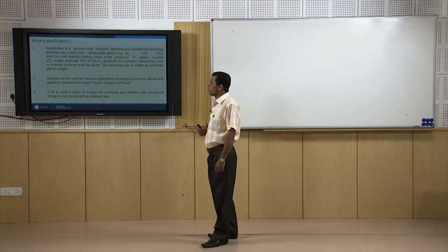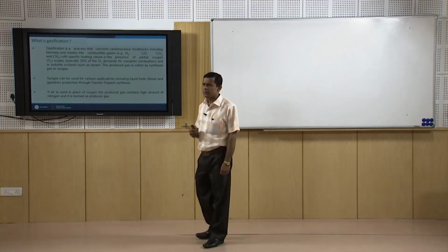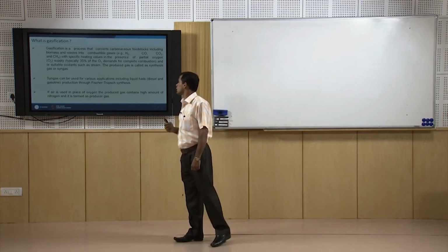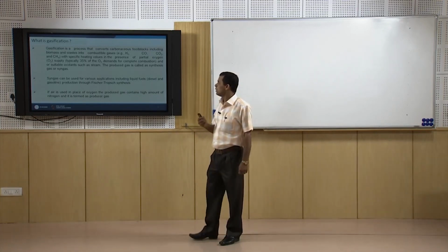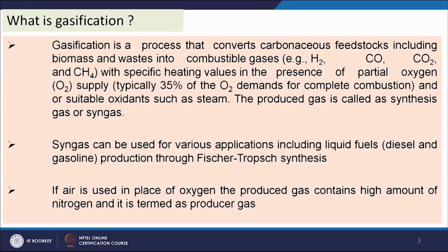Now, we will see what gasification is. Gasification is a process that converts carbonaceous feedstocks into combustible gases including H2 and CO, mainly carbon monoxide and hydrogen rich gas, with a specific heating value, in the presence of a partial oxygen supply, that is typically say 35% of the oxygen demand of complete combustion, or suitable oxidants such as steam.